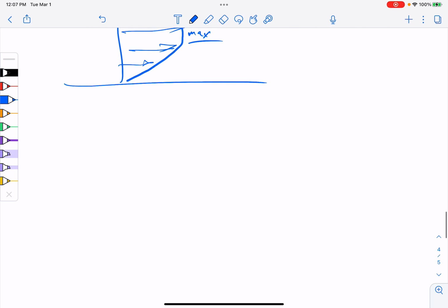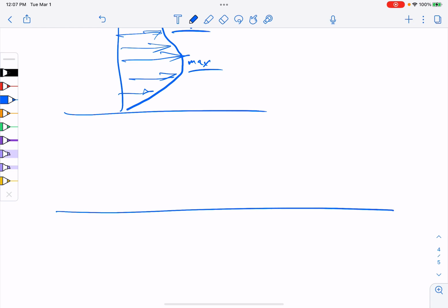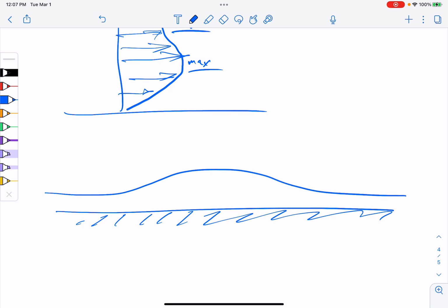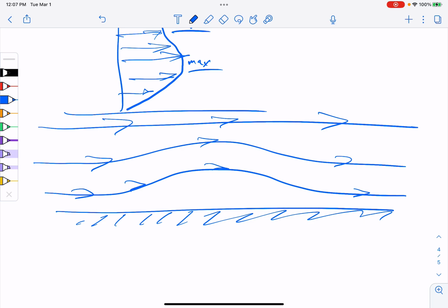So that means if I have, say, a boundary layer like this, here's the wall, and sometimes, because I have unfavorable pressure gradients, I might have a flow that comes up and has a separation bubble. So this might be a streamline. There's more flow. And it might go something like this. And this is just a separation bubble.